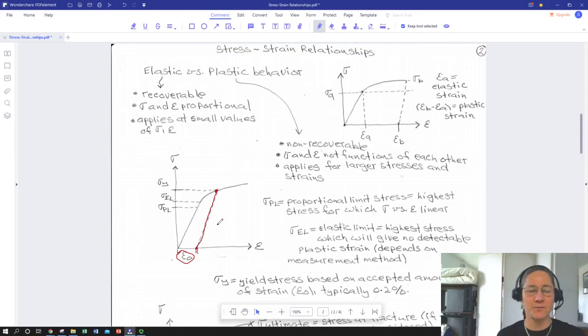It's called offset because you find it by plotting your stress-strain curve and then taking this point and drawing an offset to your elasticity line. These two are supposed to be parallel. You do not drop it straight down. That would give you a much too large value for strain, and you would call the stress too small. It has to follow a line proportional to the modulus, which is how the material would unload. It would recover that elastic strain first.